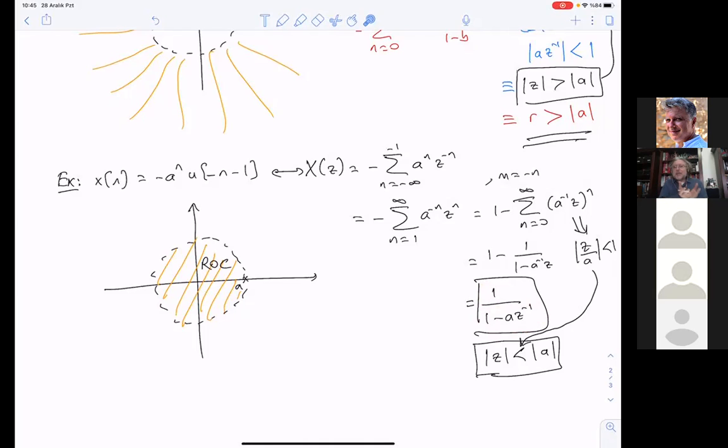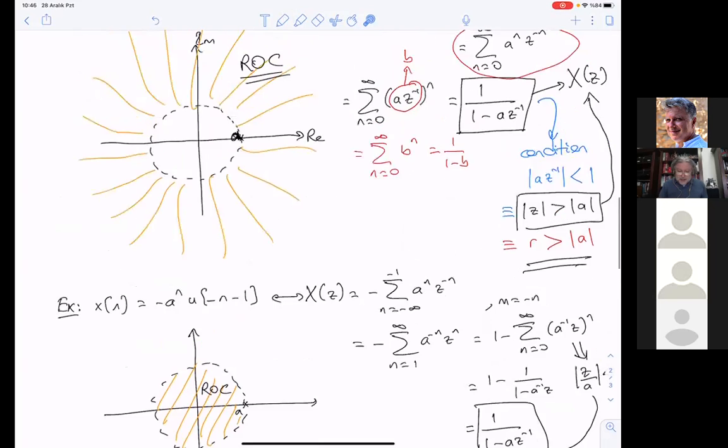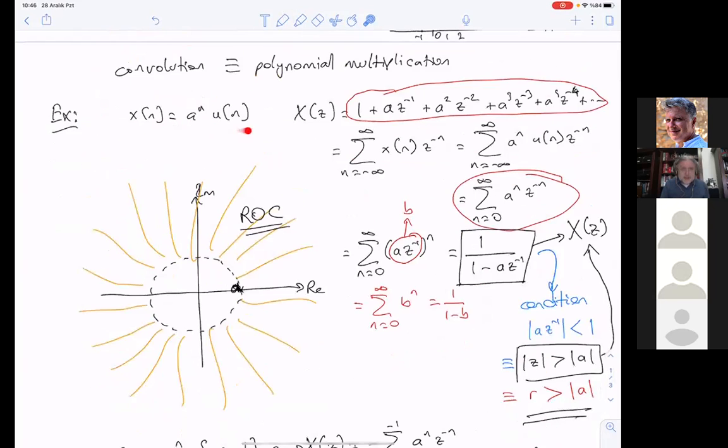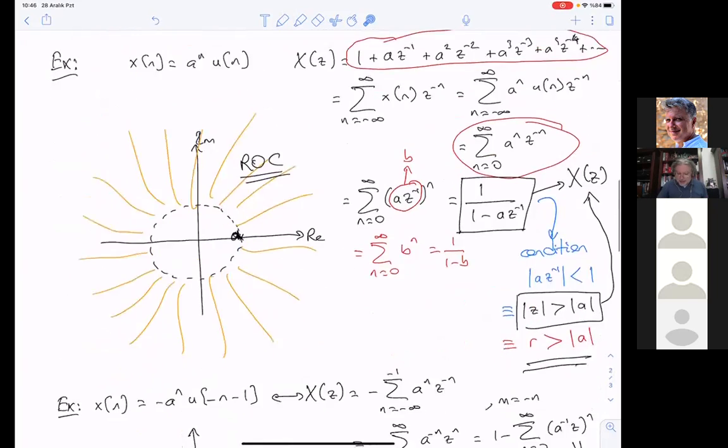You have to have a table in your hands telling you that the Z transform of this is this with this region of convergence. So when you look at your table and if you encounter a Z transform like this, then if the region of convergence is to the outside of a circle, you will say that, oops, it's here. The signal must be like this. You just give this answer immediately.